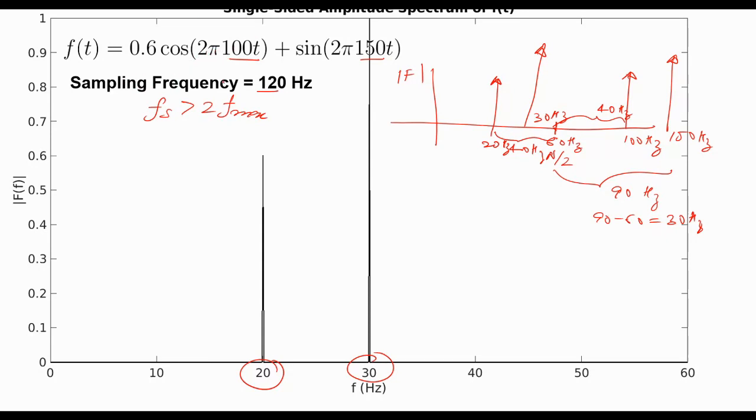What you will actually get is just the discrete signal that has been sampled. And note that the frequency components that have been sampled at a rate which does not satisfy this criterion would be aliased. And once you have a spectrum such as this shown over here, and you see peaks at 20 and 30 Hz, there's no way to recover the true frequency component.